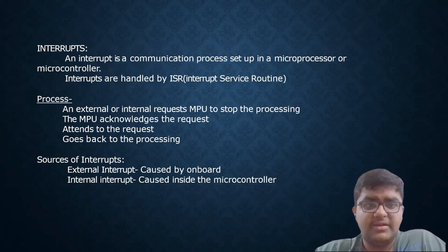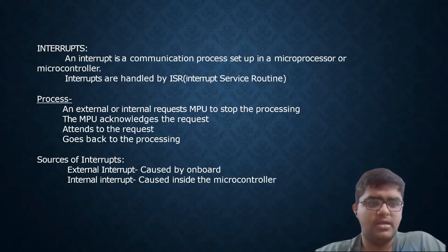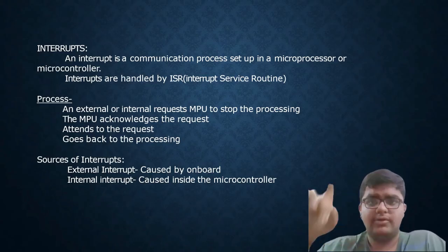Then we have interrupts. An interrupt is a communication process set up in a microprocessor or microcontroller. Interrupts are handled by the interrupt service routine. An external or internal request makes the MPU stop the processing. The MPU acknowledges the request, attends to the request, and goes back to the processing. So it's a whole routine, or you can say subroutine. Sources of interrupts: external interrupts caused by onboard components, and internal interrupts caused inside the microcontroller.